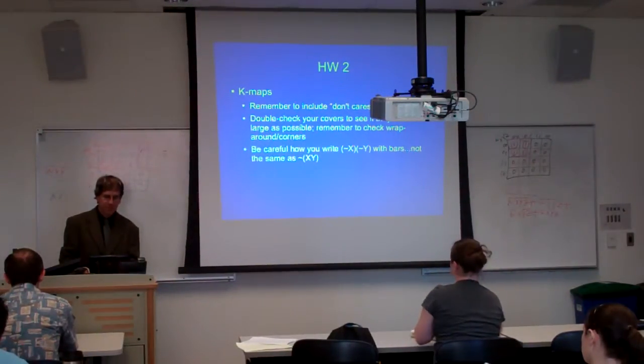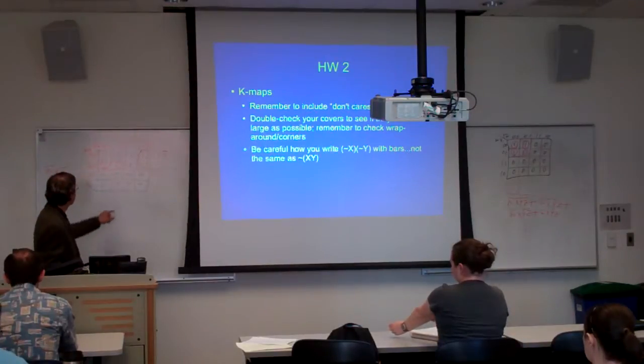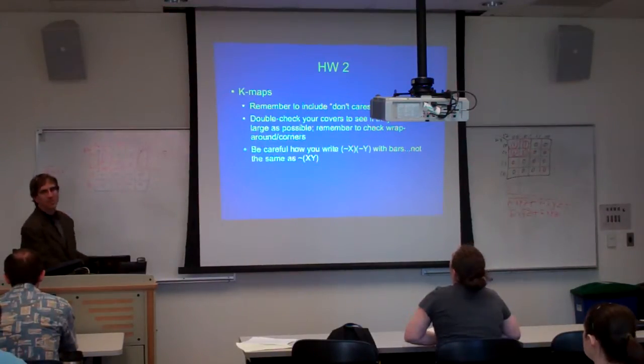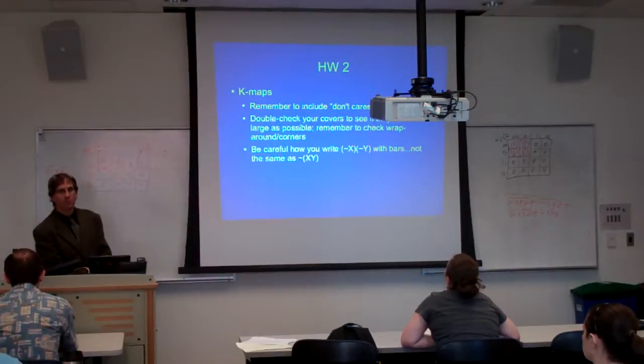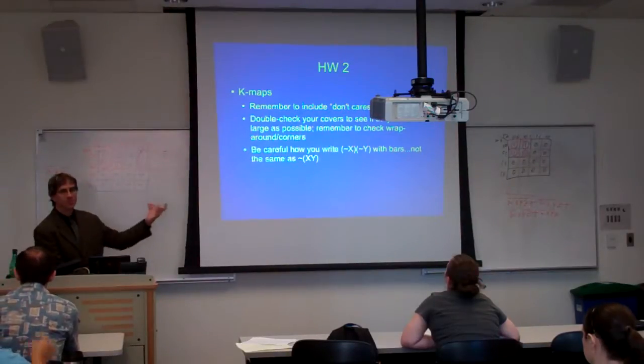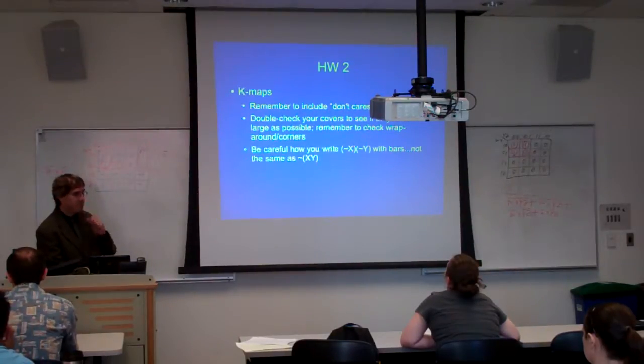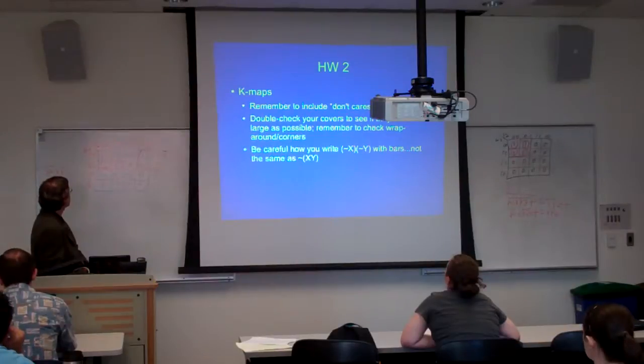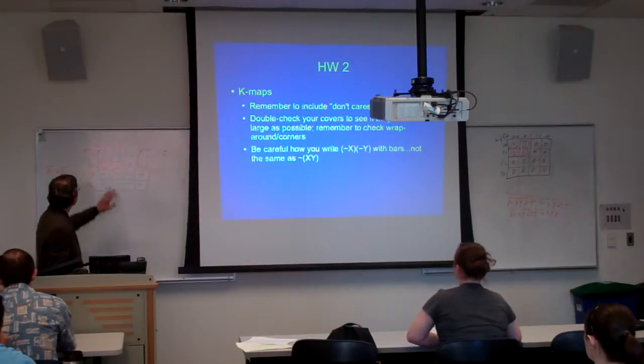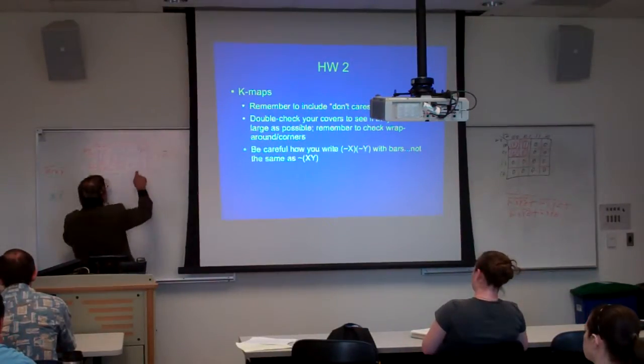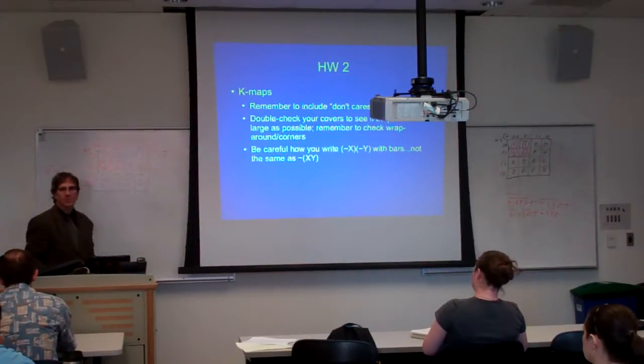Okay, also make sure you include your don't cares. Same reason, if you have don't cares, you can get bigger rectangles. Don't waste rectangles covering don't cares if you don't care about them. Don't add extra rectangles, because those are more expressions in your final answer. But if there's a way to cover those ones with a big rectangle like that instead of just the 2 of them, you'll get a smaller term.